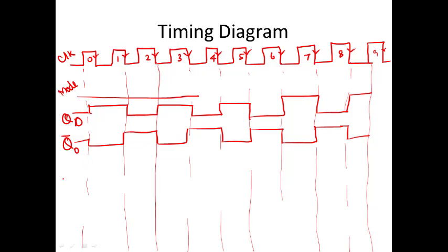What about your Q1? First let it be this clock. This is the clock initially because it's an up counter. So for Q1, this is going to be your clock. Till then it is 0, assume initially 0, and afterwards it is going to be 1 here, and this is going to be 1 here, like this.